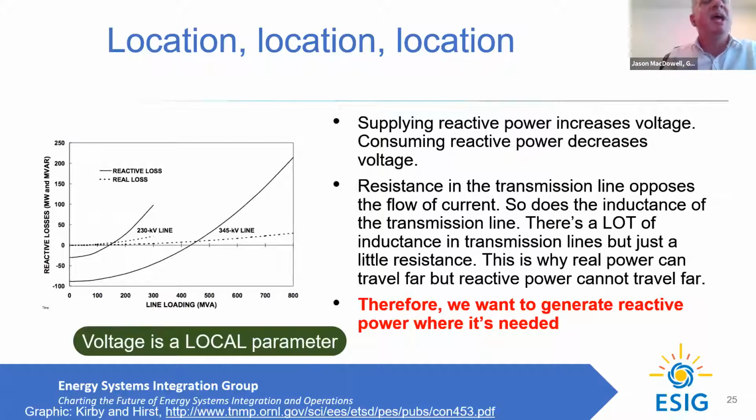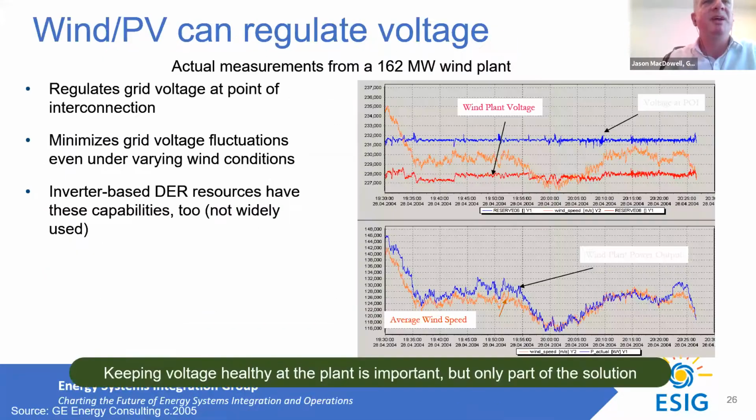And there's a lot of engineering and application work that goes into understanding if we have voltage control and stability issues on a plant-to-plant basis. Modeling, particularly of each individual inverter-based resource, becomes more critical. Modeling of an area to keep that stable is also very critical. But the biggest issue is knowing what type of model you have to use and what some of the risks are of having the system go unstable. Nick will talk more about that later, in terms of when the voltage collapses or when we have to worry about system stability.